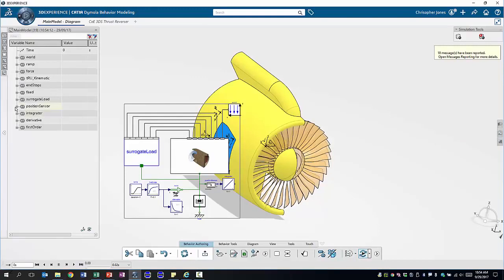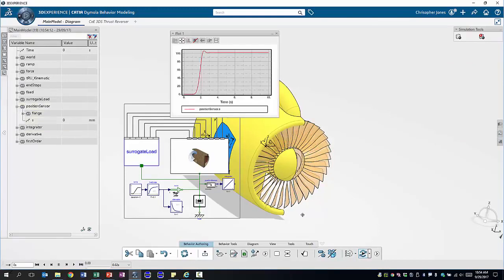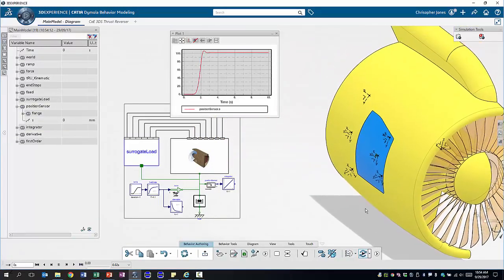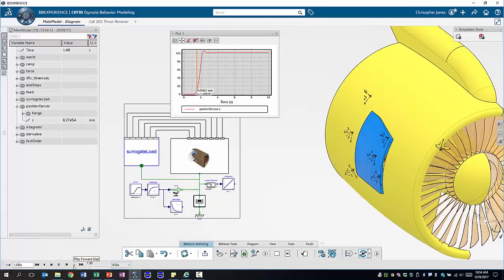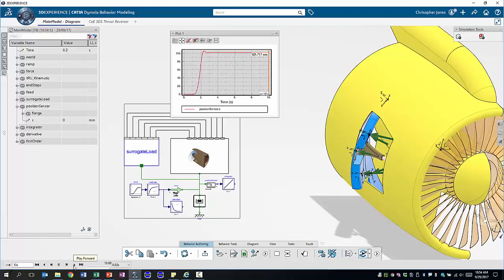So again, let's plot the simulation results and look at the resulting animation. And what we can see is that the door opens and no longer oscillates in the wind. So we've been able to get rid of the oscillation, however we can also tell that the door doesn't open completely. So the applied force to open the door is clearly not high enough to counteract the load forces which are being applied to the 6 points.